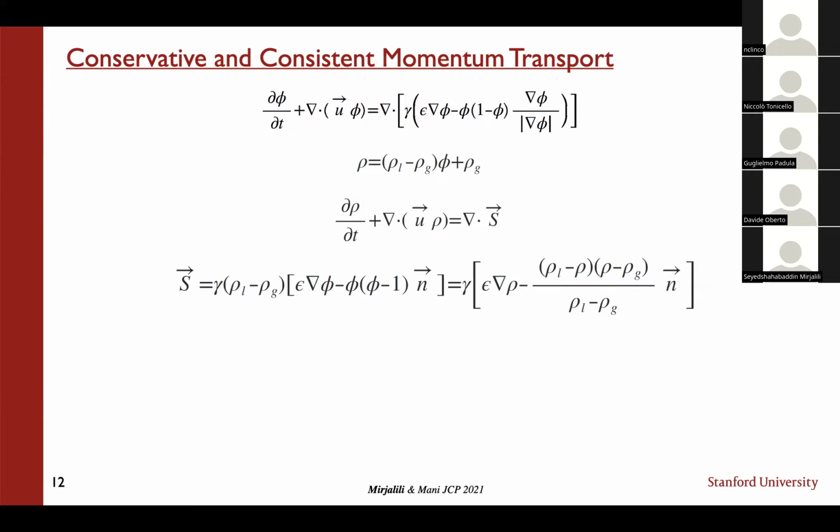If you would like to achieve conservativeness for kinetic energy, for mass and momentum, the only way is to have skew-symmetric operators, so you can adopt only central difference schemes. And in my knowledge, when you apply central difference schemes, your time step is really limited, and you also have many problems in general in the solver.